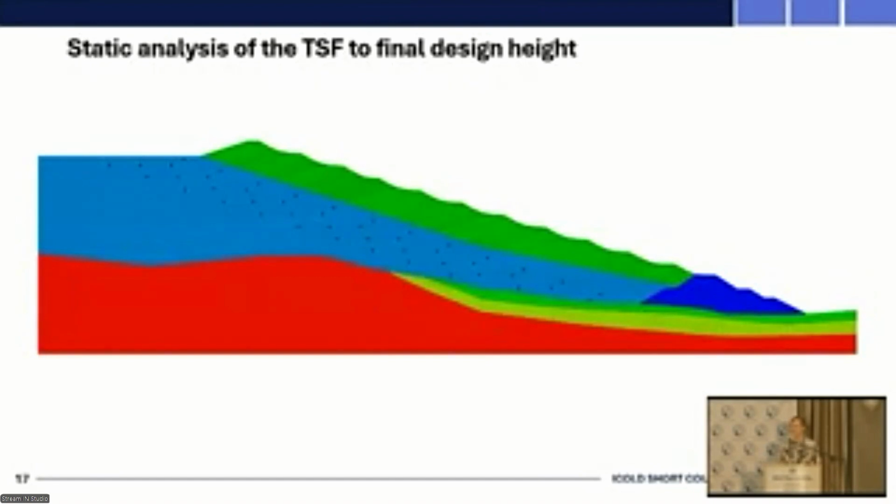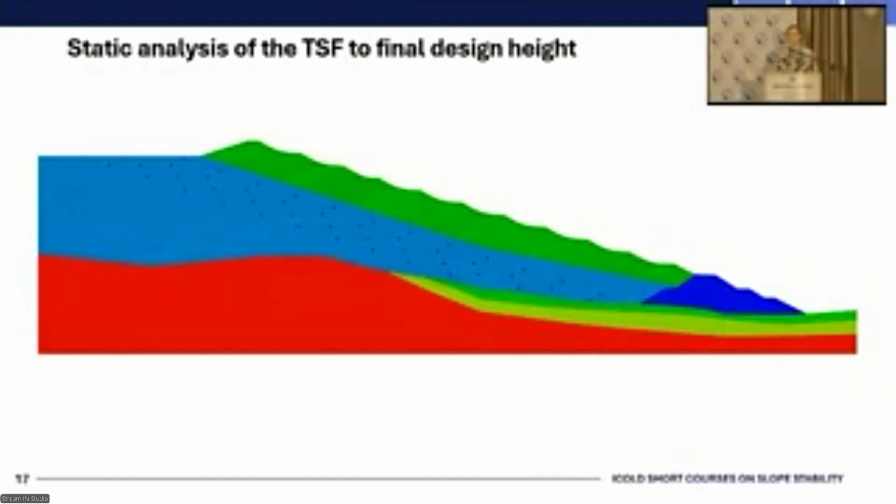Okay, so unlike the results through limit equilibrium or the strength reduction method or something like that, where you get one output that's a factor of safety, that's not really possible for these deformation analyses using critical state soil mechanics. And so what we prefer to do is to look at discrete points in the model and then query their stress and state during the simulation, so during construction of the facility and then as loading scenarios are applied to the facility.